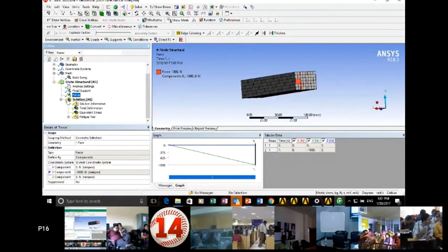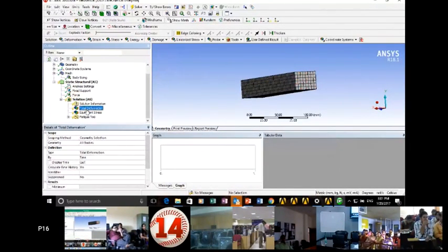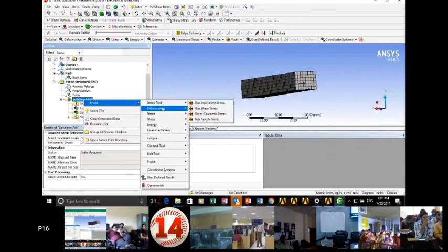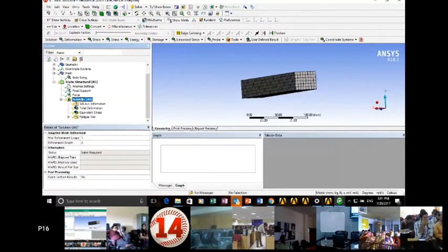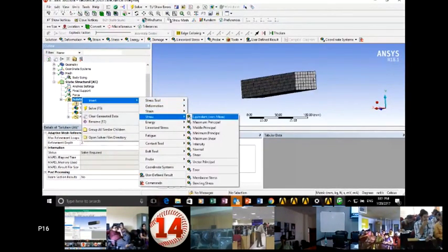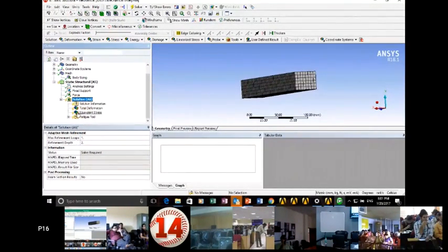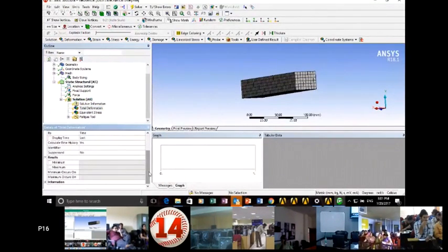Now, for carrying out that independent study using what-if analysis, we will simply create a set of varying values of forces and mesh sizing, and based on that we'll get different values of total deformation and equivalent stresses. Now over here we'll parameterize. We have evaluated the results for total deformation as well as for equivalent stresses. Now I'll parameterize the maximum and minimum value of equivalent stresses and deformation.